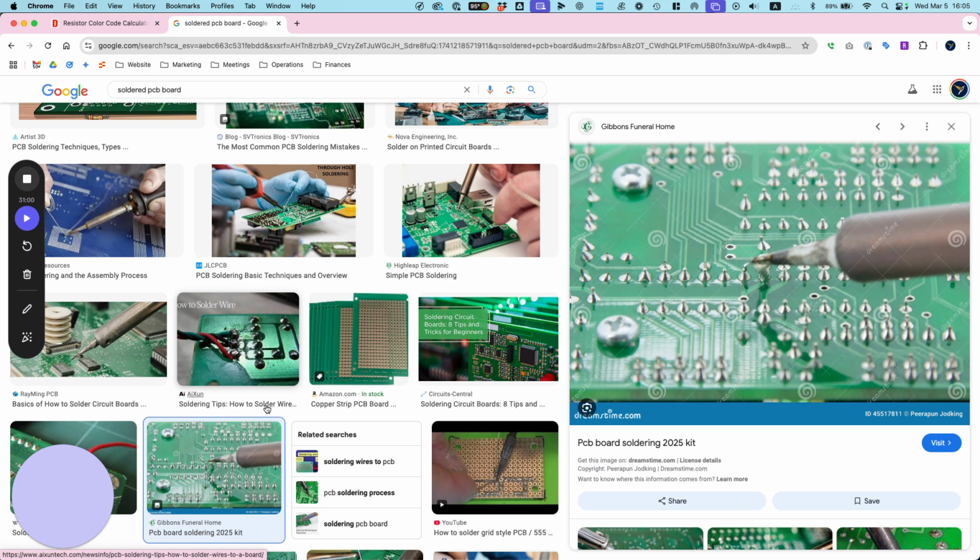Okay. Right now the soldering iron is not really melting it very well, and that's because I need to tin it. We don't have flux and everything like that. The flux would help it flow better, but we don't have all that stuff. So I'm going to need to tin it first. We want it to be nice and shiny. Right now it's kind of dull.